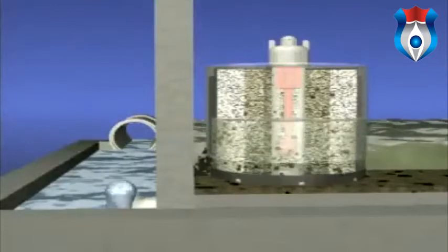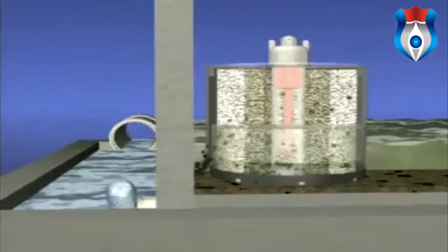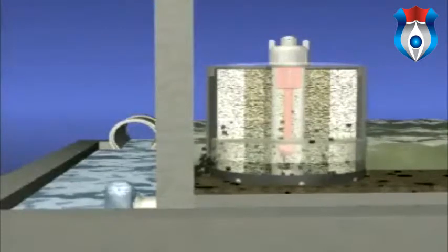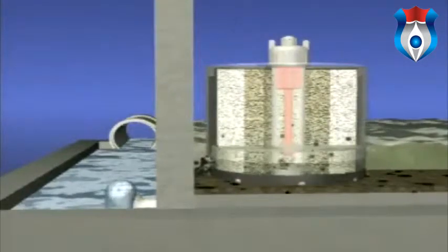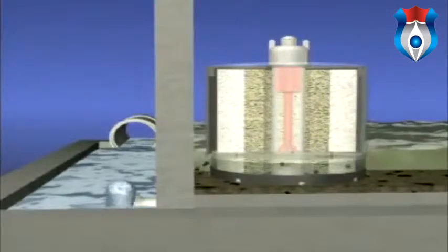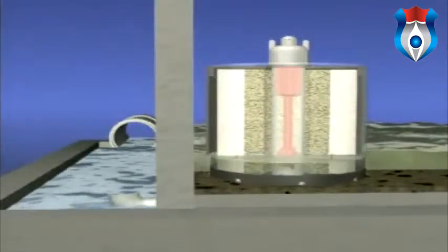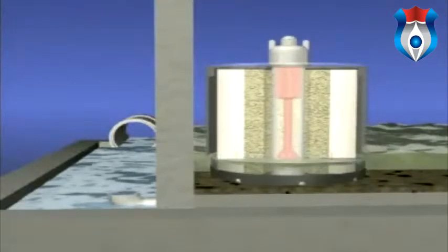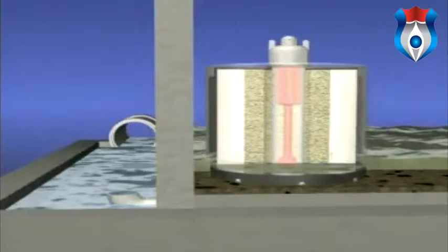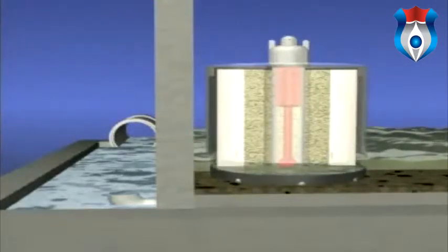As the water in the vault continues to drop, air bubbles rush through the regulators into the cartridge as the water under the hood is released. The bubbles agitate the surface of the filter media, causing much of the accumulated sediment to drop to the vault floor. This patented self-cleaning mechanism also increases the effective life of the filter.